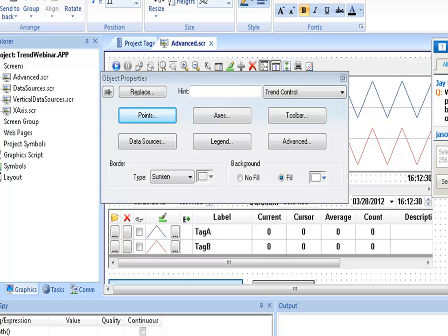The way it works is typically the controller, the physical data acquisition hardware, keeps collecting the data and saving this data into a local file in the controller, and InduSoft reads this data in blocks or receives the file via FTP and then exports this data to the database.